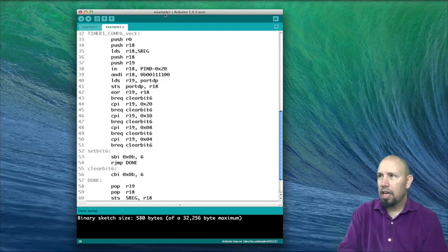I'm going to save here R0 and R18. So I push those. Okay. Now R0 actually I don't plan on using, but I'm going to go ahead and save it anyway. That's just a good practice. Maybe it's superstitious to do that, but anyway.